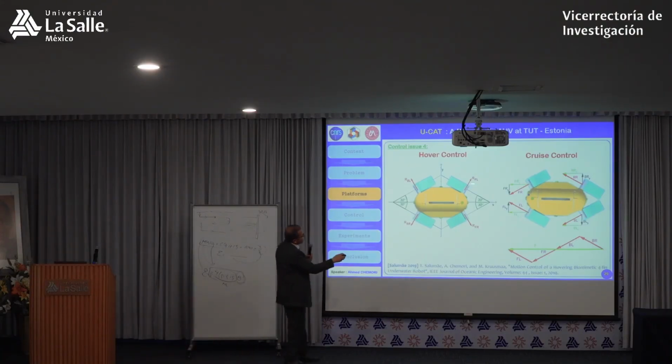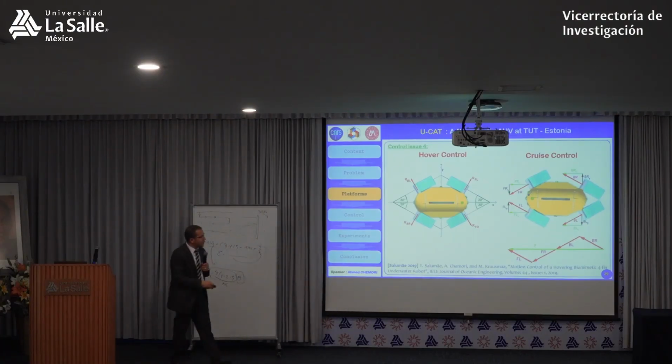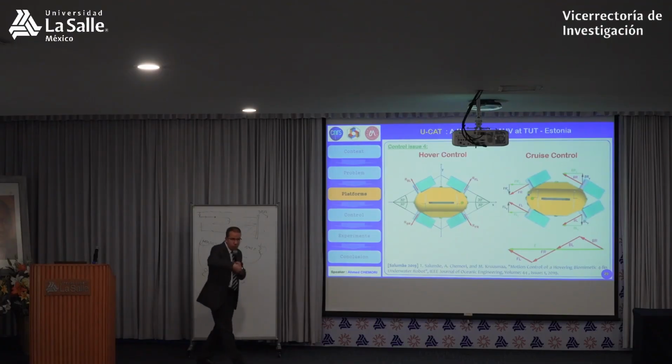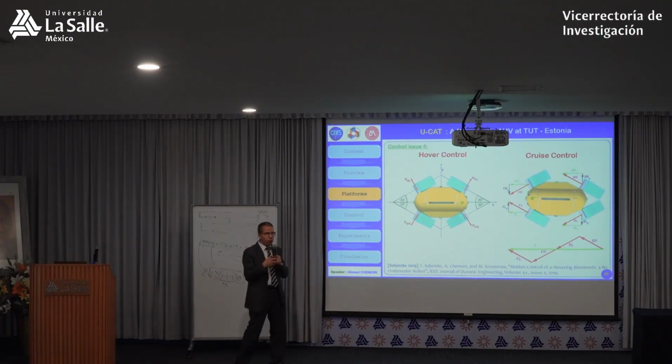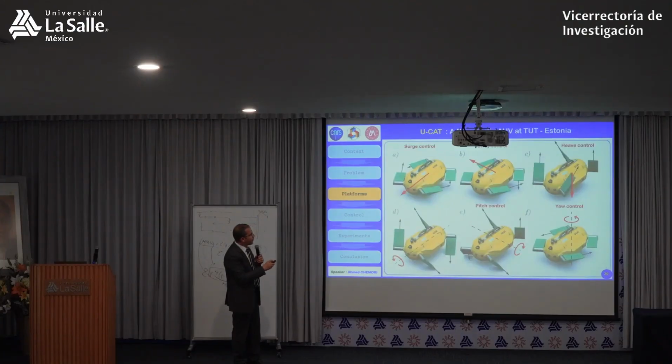Because here, the 2 fins, the front and the rear fins, compensate each other, and you can stay in a stable position. This is why this hover mode is more appropriate for this kind of task. However, for this one, it's more performant. You have bigger force to push the robot forwards. Nice, let's go ahead.